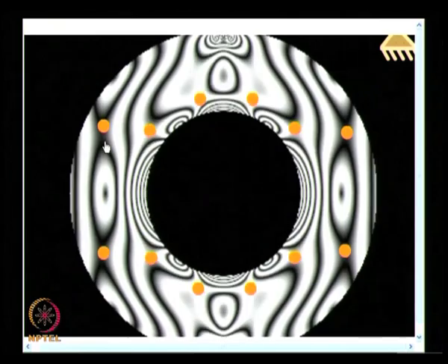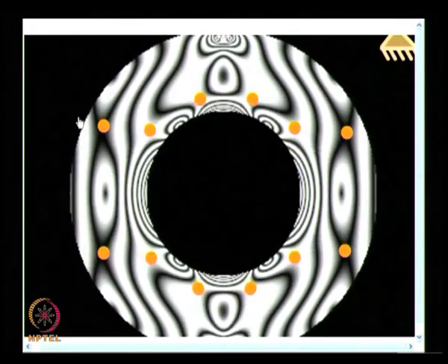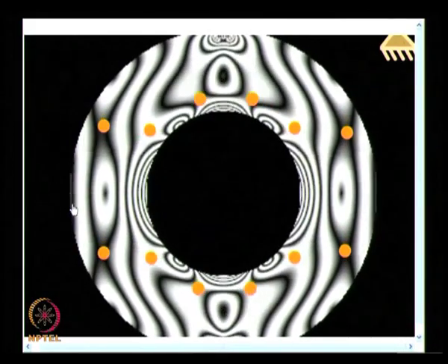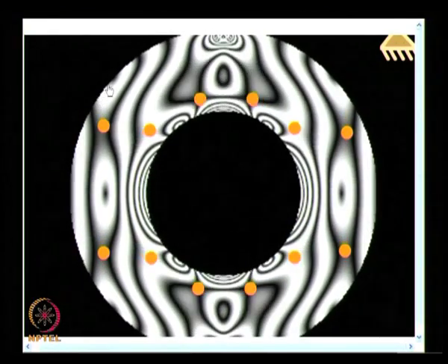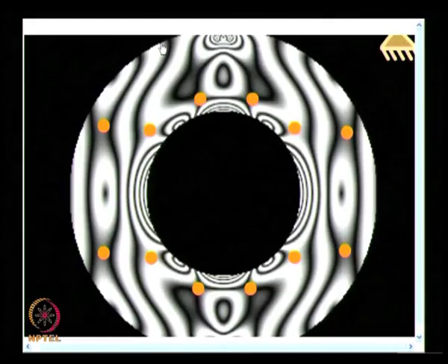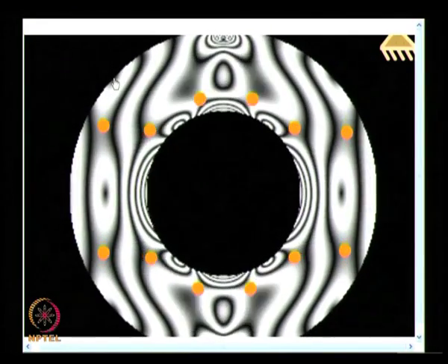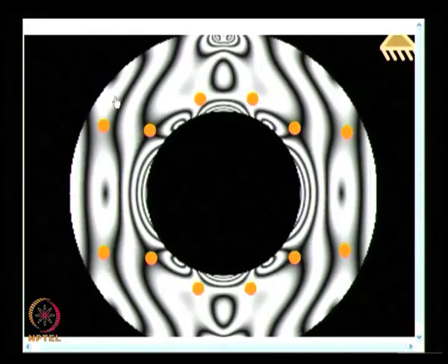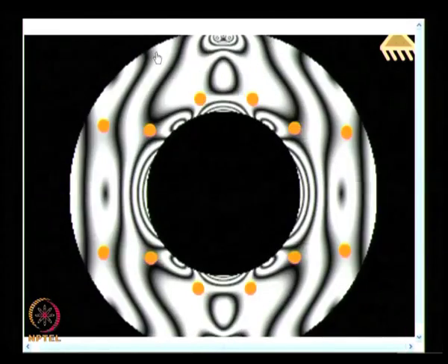And all along we have not bothered about what is the sign of the boundary stresses. We have looked at beam under bending, we have looked at ring under diametral compression. How do you identify whether the sign changes? We will have a methodology to find out separately. We can also look at from a fringe feature. Suppose I have a 0th fringe order on the boundary. How can you pass through 0? When I pass through 0, I need to have sign change.